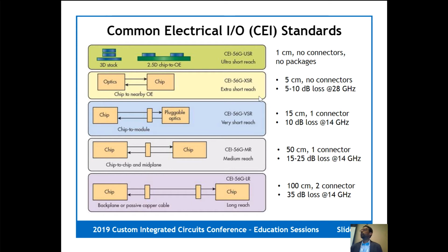So those are the two exceptions that I mentioned earlier to PAM4 modulation, where for these really short reach links, you don't want to incur the latency and power overhead of FEC, and it's actually possible to close the link budget without that. And so those are the only two cases where NRZ implementations exist. Everything beyond that has transitioned to PAM4.